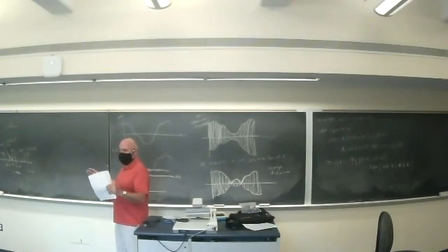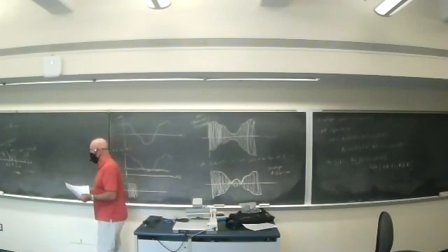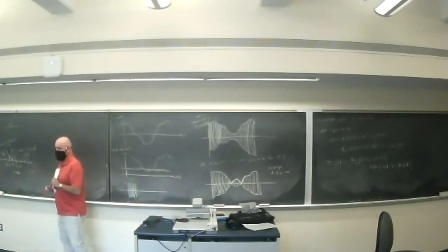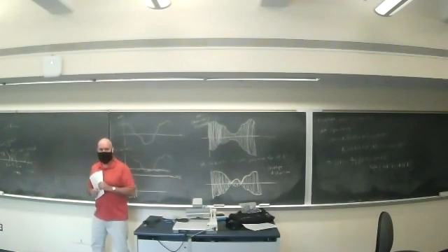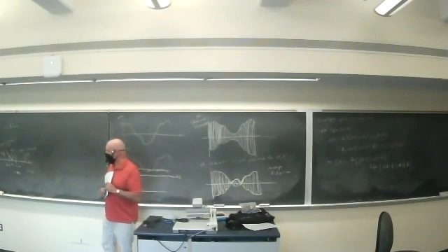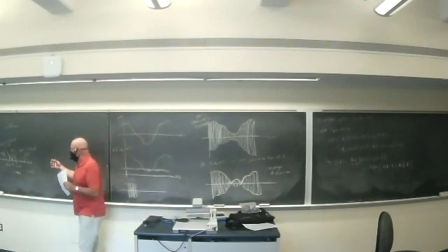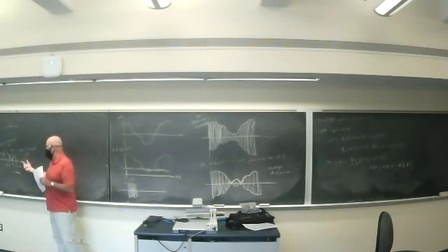Okay. FM has a much wider bandwidth. The frequency spacing is 200 kilohertz there. Now again, for FM we actually have to calculate the bandwidth differently than for AM. But standard AM radio is not good for music, and the reason is, there's nothing inherent about AM.